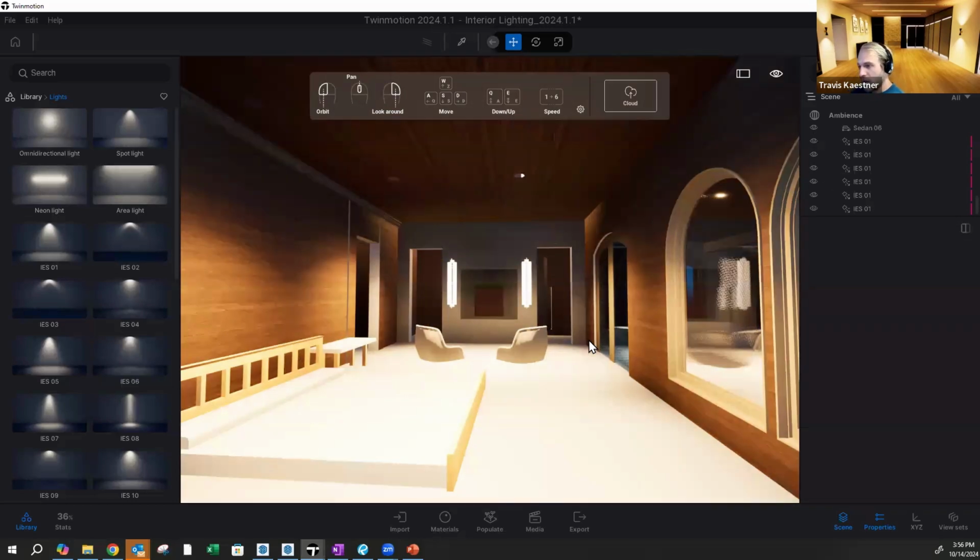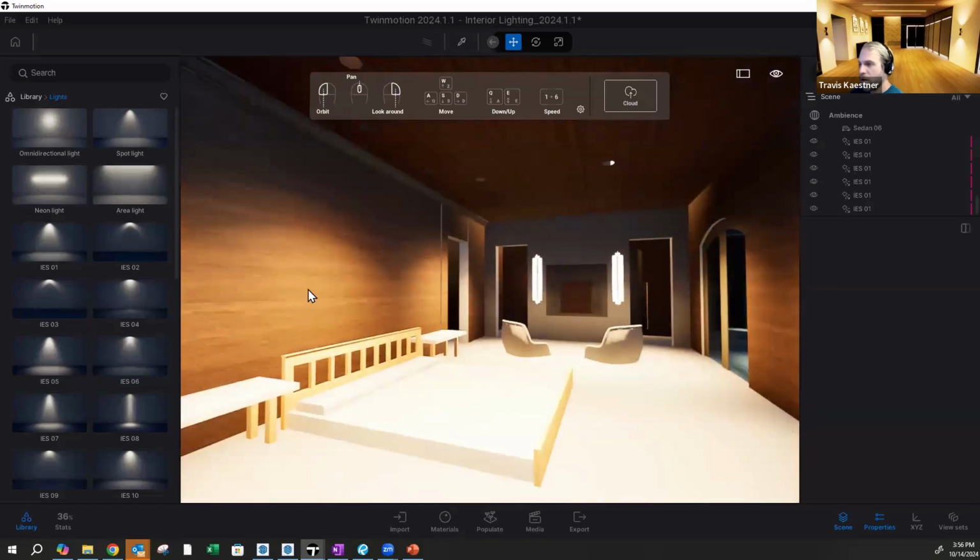So that's the other way we can add ambient light into the space, by reflecting or bouncing light. Instead of just the direct downlights laid out in the ceiling, maybe we can layer in lights with accent and task. That's why you see this light on the wood: light waves hit the object and then bounce back into our eyes, and part of those light waves get absorbed and part come back to us. And that's what helps dictate what color we see.